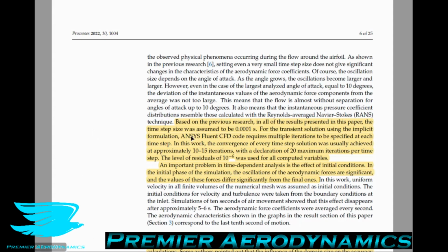So let's say you have time step 200, and the CFD simulation has calculated that. Instead of moving to time step 201, we actually do inner iterations to make sure that the solution has stabilized a little bit, and then we move on, because when we change the time step, the flow obviously changes quite a lot. And we want to make sure that, in mathematical terms, the gradients of the different flow parameters are not too great. We want them to be quite low, which means that the flow is not changing too much compared to our time steps and/or when we're changing the flow.